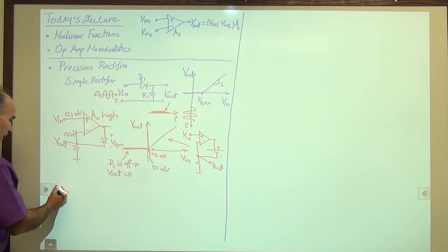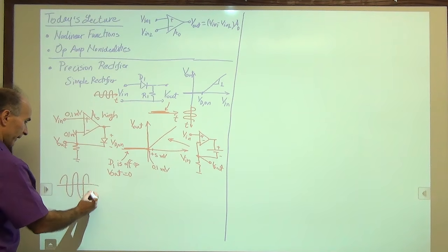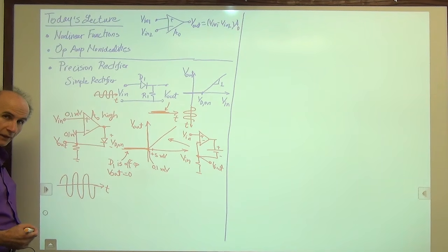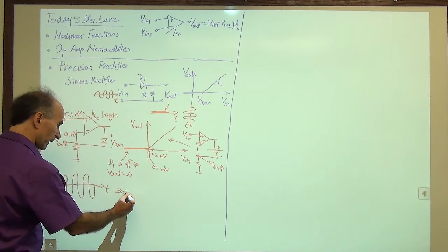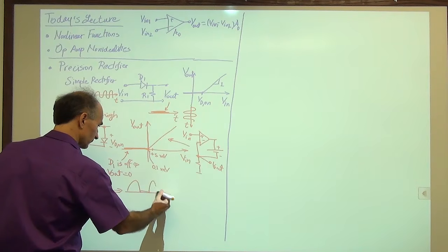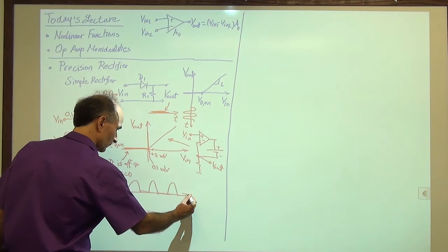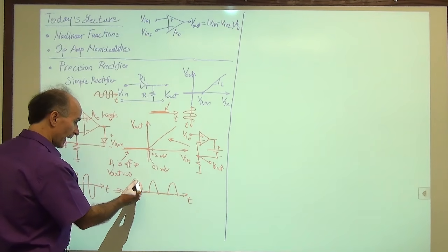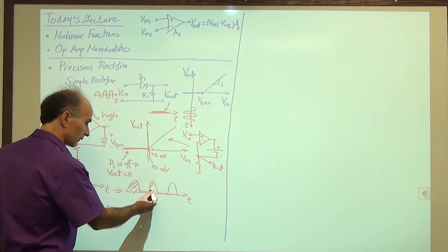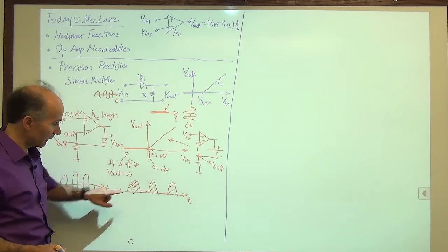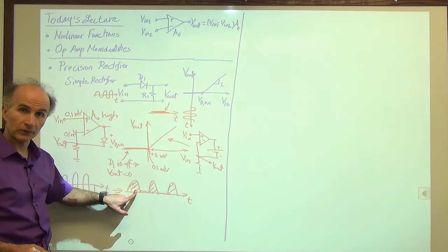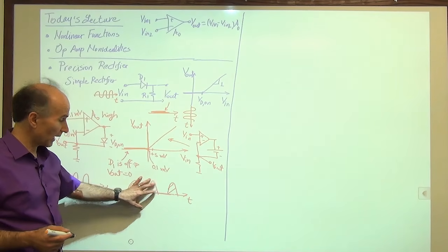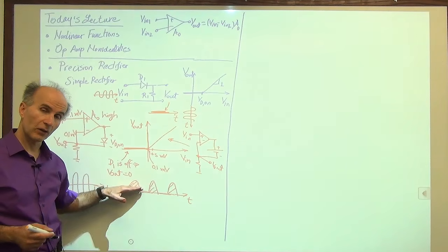Well, the way we do this is that if we have this waveform by itself, with linear operations, it's difficult to determine this amplitude, so we have to have some nonlinear operation. So what we do is we first rectify it. Okay, and then we observe that if we find the average of this waveform, meaning this area divided by the period, obviously this area is in proportion to this amplitude, right? So first we rectify, then we find the average, meaning we low-pass filter it, and that gives us an indication of how large the signal is.